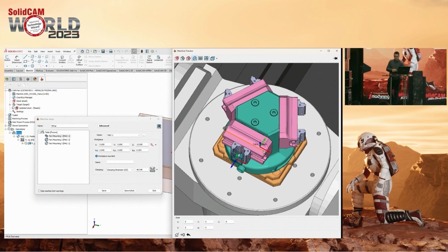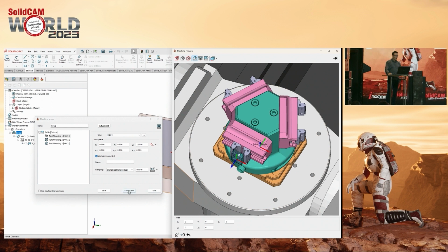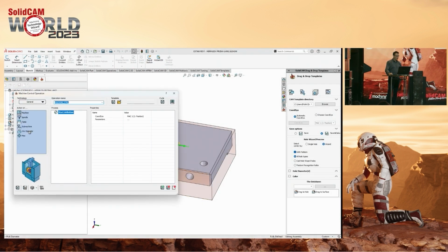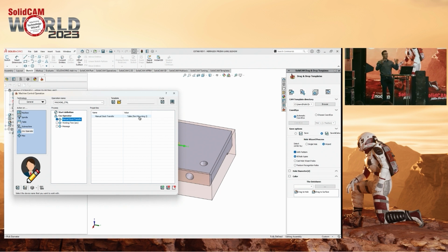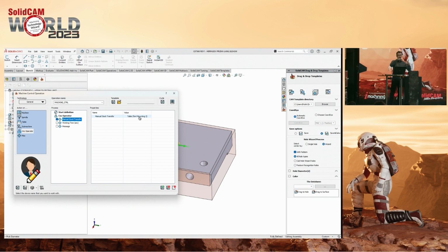3 mounting points. What does this allow us? When you have 3 mounting points, you are allowed to create a new MCO, and you can take the CNC operator, and now you can move your stock from one vise to another vise. The same philosophy like in the mill turn, when we have a main spindle, sub spindle, at the end we add a new workpiece, and we are going to see 2 parts machined together.